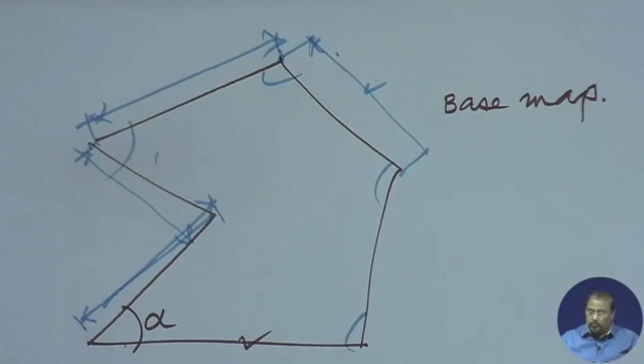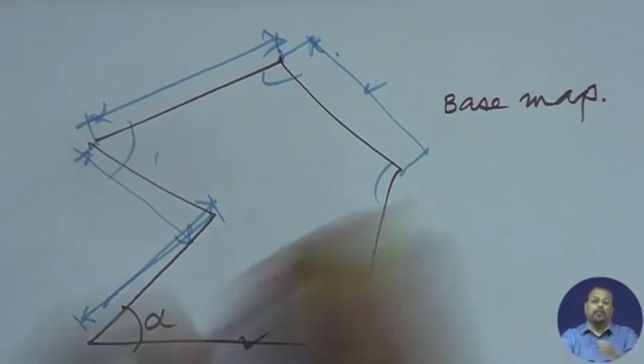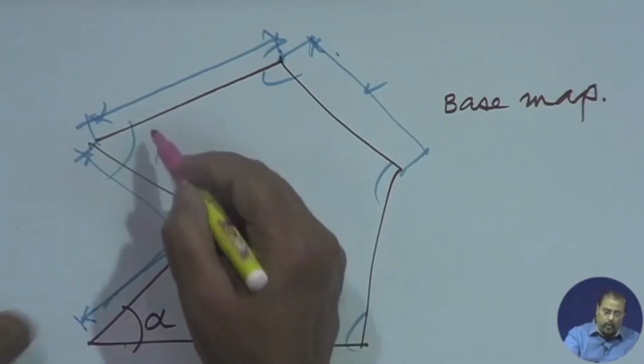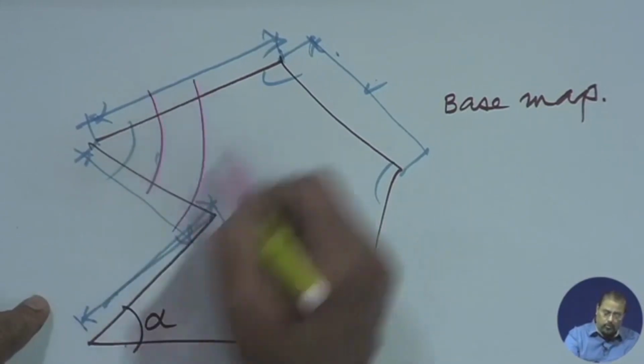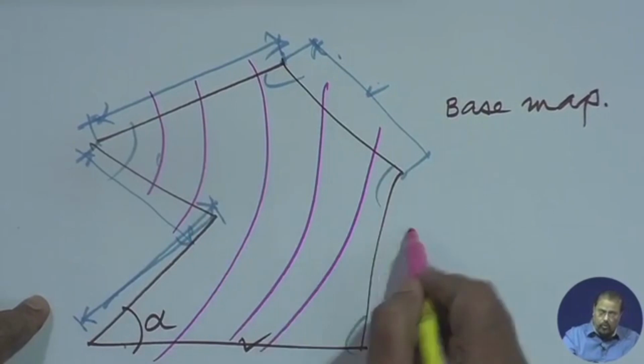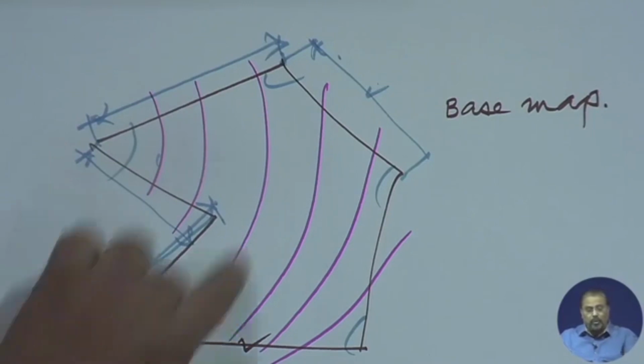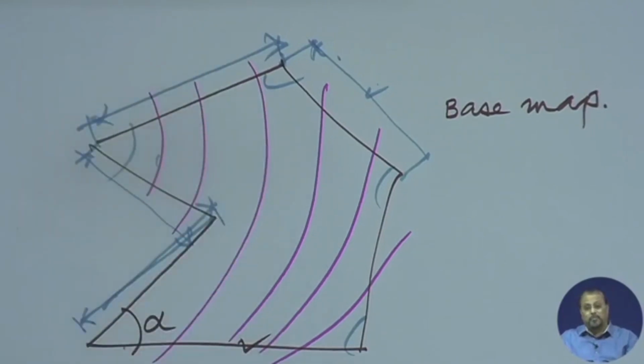What kind of features? First of all, the topographic features. If this particular area is not flat, it is contoured, then in such a case the topographic factors you need to have are contours. These contours are not a physical line in sight. These are notional lines of uniform elevation along that particular line. They are not lines seen on the site.